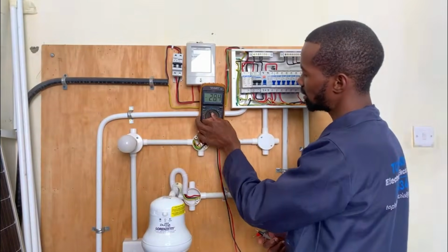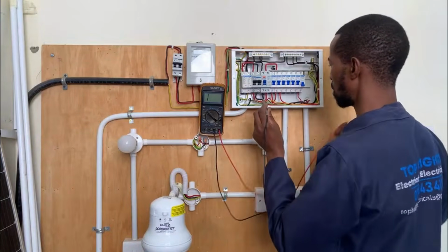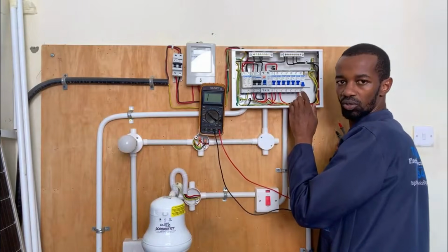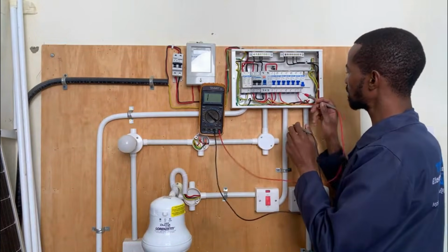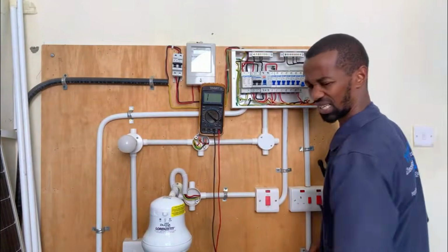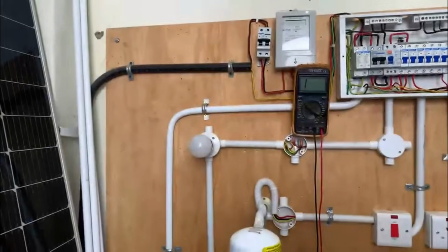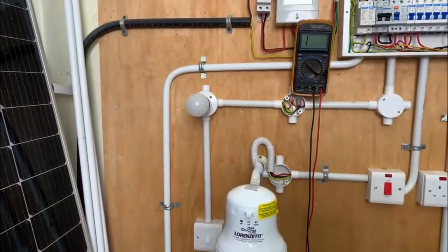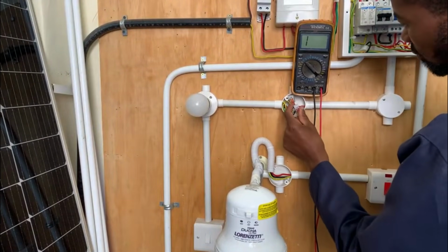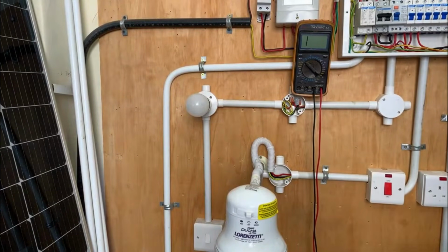So you place the indicator of the multimeter, and after isolating the circuits, you now take the readings. You see from the MCB, you have the outgoing to the specific circuits, okay? So you take a reading between the phase or the line and the neutral, right? So let us come up with a real life scenario. If at this point where you have that JB, assuming that there's a short circuit here, that can cause the MCB to trip, right? So if these live and neutral cables here are in contact with each other, it can cause the MCB to trip.